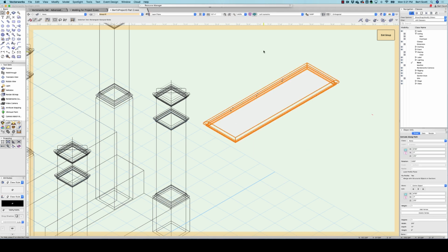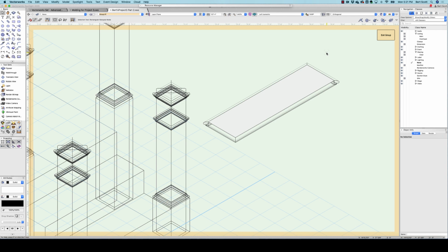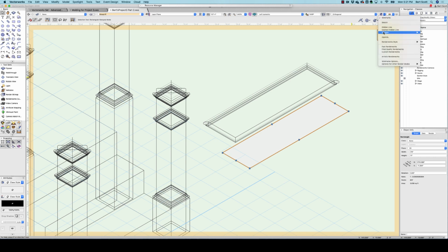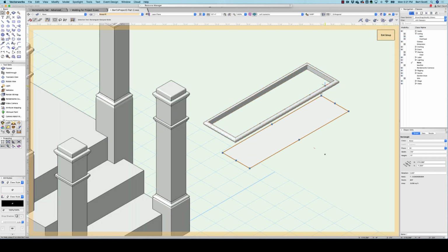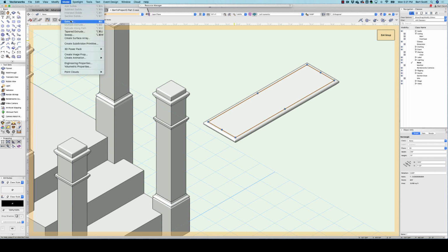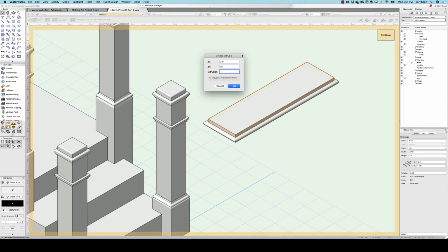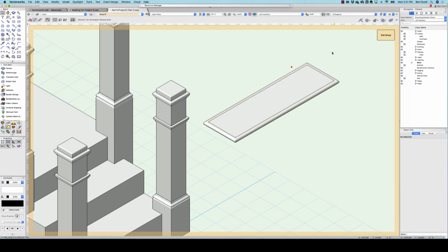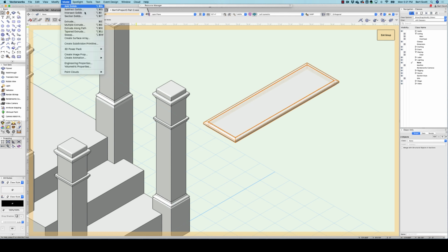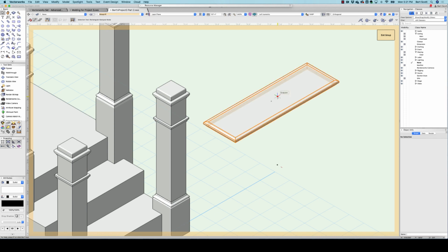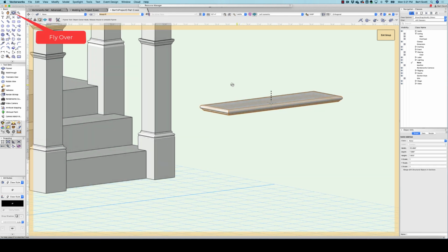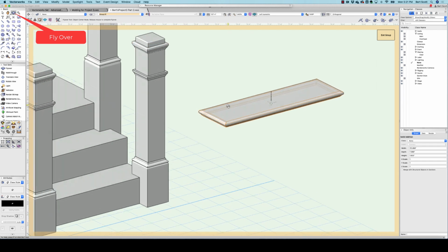We're going to select the rectangle as the path and make sure that the profile is fixed. Click OK, and we have almost a step. What we have is the molding around the step, but we're missing the step itself, hence the second rectangle. So now I'm going to put that rectangle back where it was, and I'm going to extrude that down an inch, Model, Extrude, -1 inch, and then I can select both of those things and add them together. Model, Add Solids, and now we have our stair with the fancy molding.